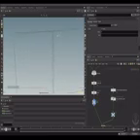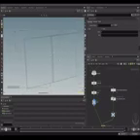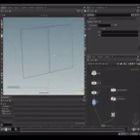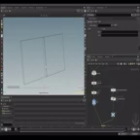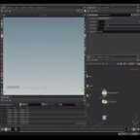First, each primitive, in this case a polyline because it's a line, will have 2 points. Each point will have the name of the piece we want to constrain. We can either connect packed or unpacked pieces, but I recommend you use the unpacked ones because it will be more accurate. Then we need to set 2 primitive attributes, the name and the type, but we'll see this in a second. There are many ways to create these primitives, these polylines, but the most useful is using a connect adjacent pieces.